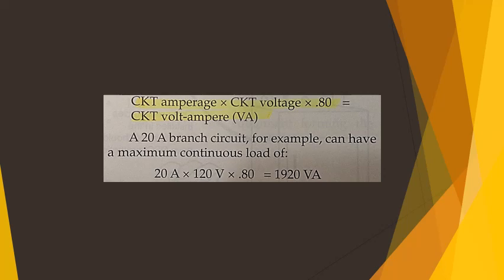While this is clear cut as far as the total wattage per circuit is concerned, some other considerations must be included in order to determine the number of outlets for each circuit. The load for each lighting outlet can vary considerably. Although some lighting fixtures, like fluorescents, draw a constant load, others do not. Most lighting fixtures can accommodate 25, 40, 60, 75, 100, or 150 watt bulbs.